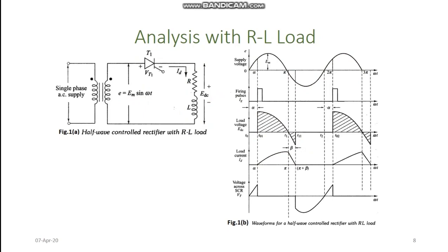If we look at the voltage waveform across this silicon controlled rectifier, we will obtain a waveform something like this. For the time interval 0 to alpha, when the gate of this thyristor was not triggered, whatever the input voltage was started to develop across this thyristor, and is shown here. Now when the negative cycle arrives, the conducting angle of this thyristor has increased from pi to pi plus beta. Hence the voltage waveform will be something like this, that is from pi plus beta to 2 pi.